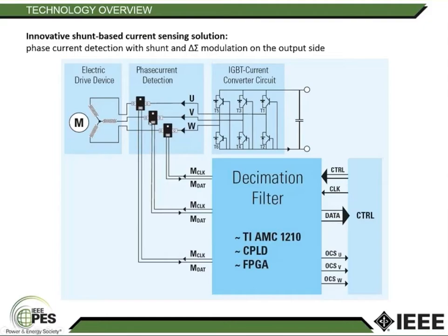So they're located right here too. The difference is though, as we deal with a resistive measurement principle here, so we measure a voltage drop over a very low ohmic resistor, those modules have to be integrated into the circuit. Means you physically have to open your circuit and integrate those modules onto the current bus bar.